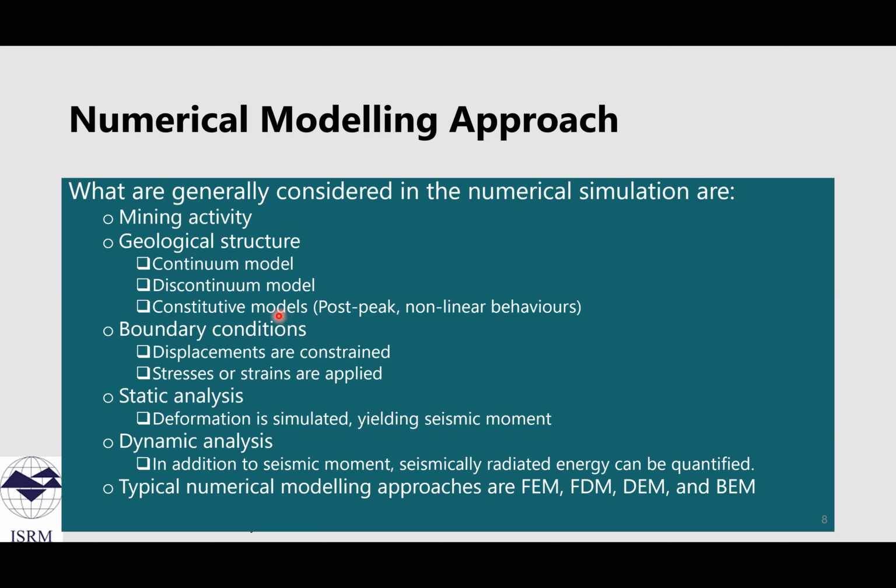So as can be seen from these examples, sometimes the conventional numerical modeling method does not yield a reasonable stress state at the seismic source region. This means that the simulated stress state is far below the critical stress state estimated from commonly used failure criteria for the seismic active region in geological structures away from the active mining area.